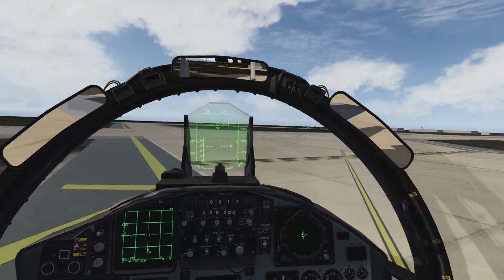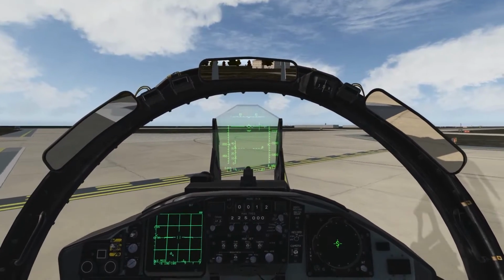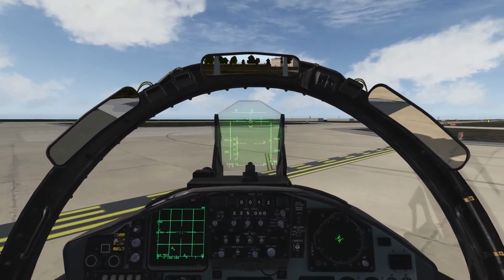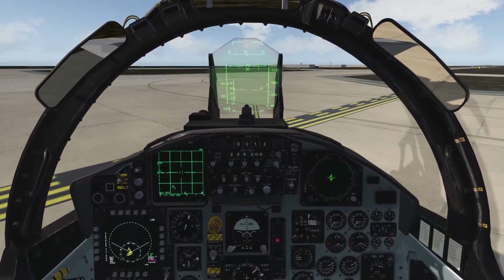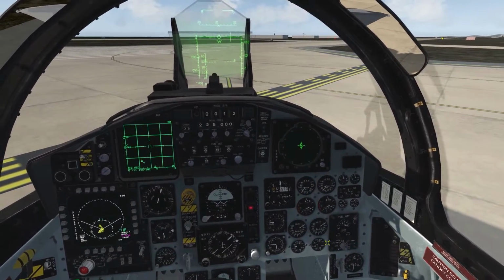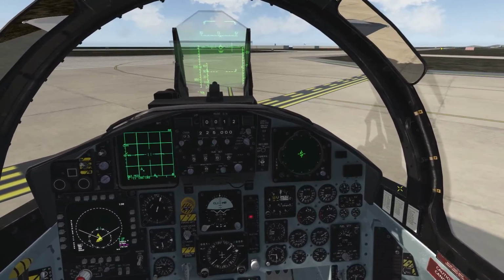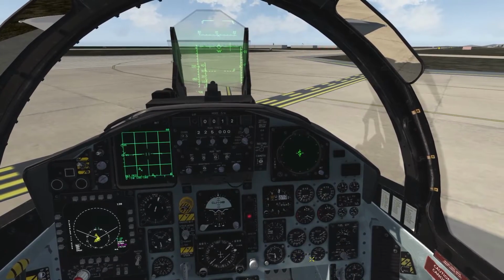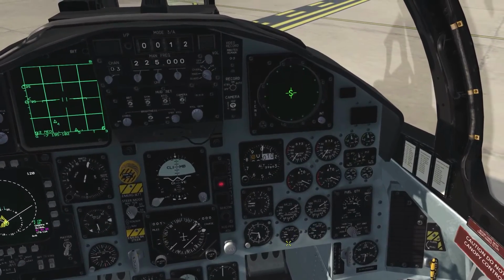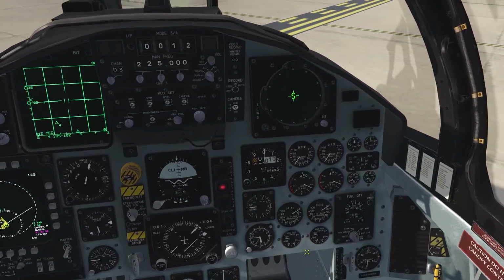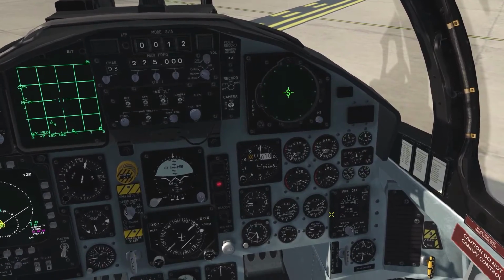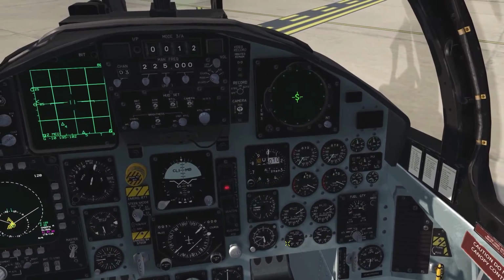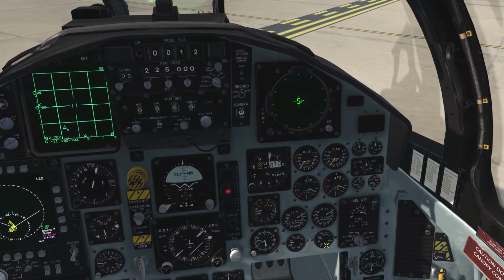So a normal takeoff in the Eagle is going to be brakes on, set thrust 80%, and check your engine instruments. For a mil power takeoff, the nozzle should remain below 30%, and max AB, as you add AB, should get progressive thrust, and the nozzles should open up.